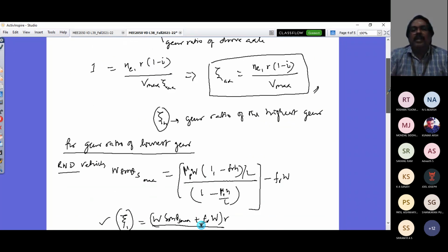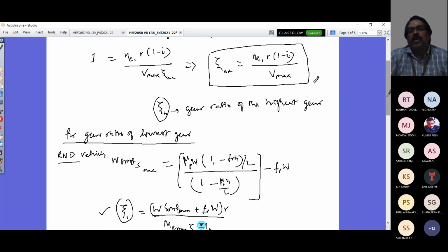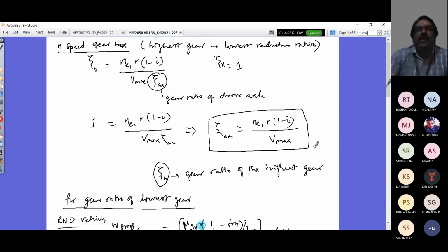Of course, for the lowest gear, the condition is to look at how good your vehicle is at climbing a slope of 33% at lower speeds, and at higher speeds, on a gentle slope of 0.3% at say 90 to 100 kilometers per hour. If your vehicle is able to go, then it is a vehicle with good accelerating performance. So these are the bases that we have seen. The advantage of having your IC engine along with your transmission system is that it could provide an ideal power requirement.